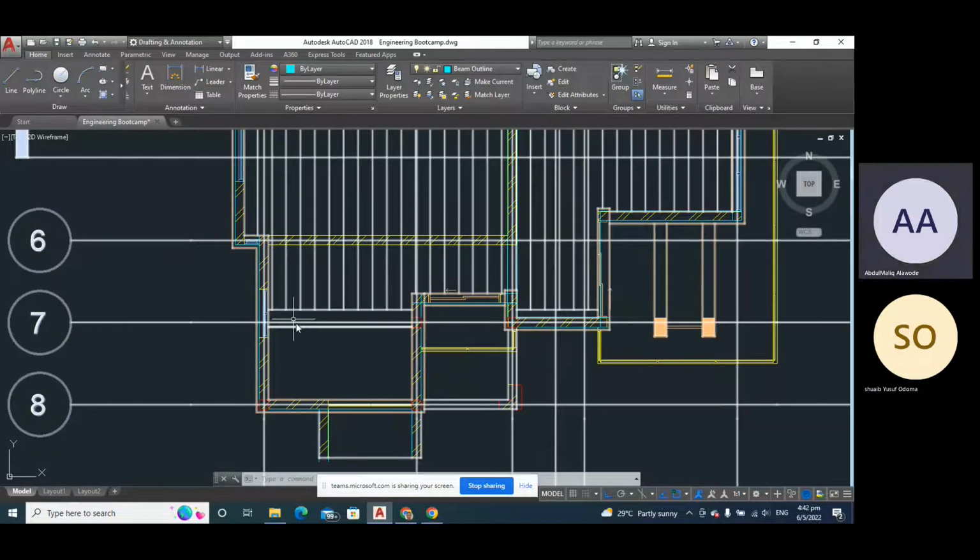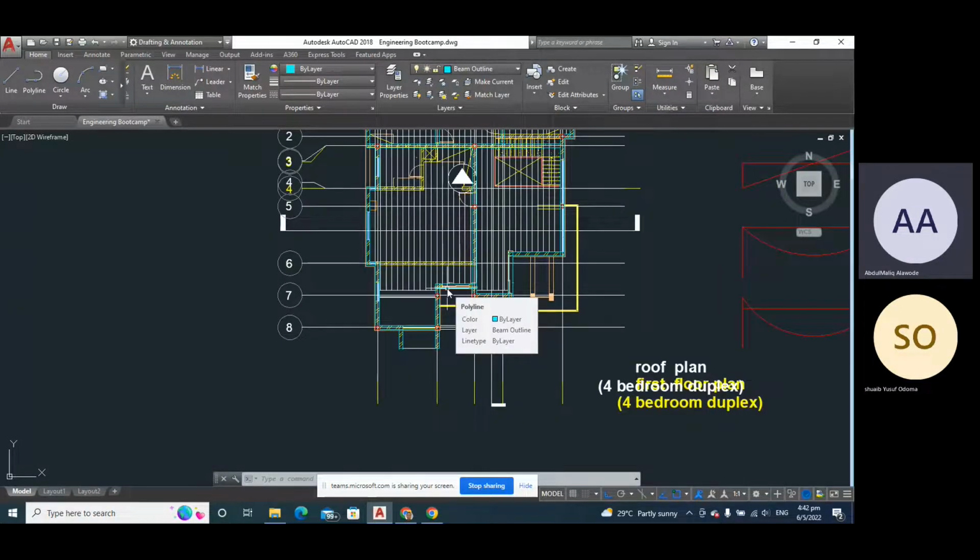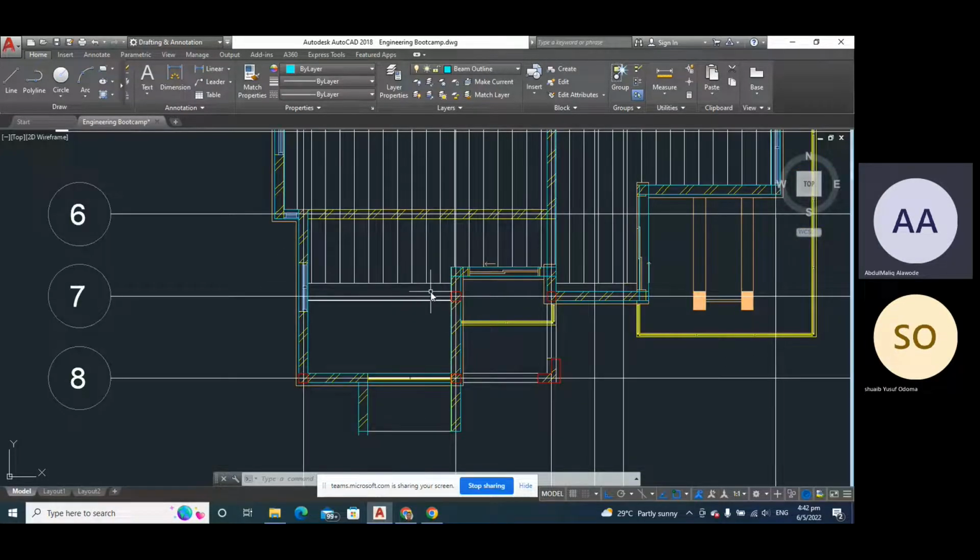So here now, it is advisable that we have an upstand beam. What I mean by an upstand beam is a beam that will go up above the slab, let's say 300 mm or 250 mm, as the case may be, depending on how the engineer wants. But I prefer minimum 300. With that, there is no rain that will exceed that, so far as we still have drain here. If it's going into the system, you now know the roof beam has done its own part. It's just that probably the drain is not working perfectly.